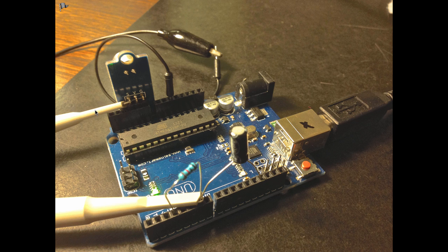The yellow trace will show us what's coming out of the microphone at pin S. And at the same time, we will look at the serial monitor and see what is printed. And so what you will see is that as soon as the voltage that's coming out of S exceeds the voltage that we have at the reference pin, then we will get the time since the last clap printed on the serial port. Okay, let's do it.